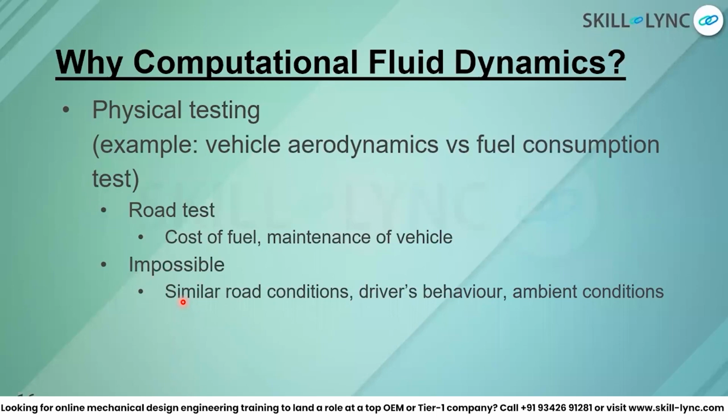That can affect the vehicle aerodynamics. So if you're testing fuel consumption for the driver plus all passengers, you need to have those parameters every time you go, because the load condition will change, the ground clearance will change. You can do those tests every time you go on the road, but that will cost a lot.